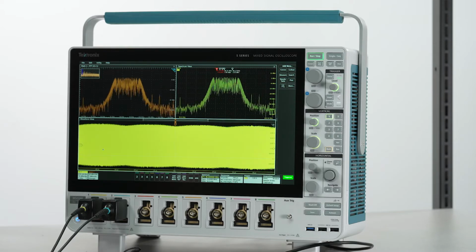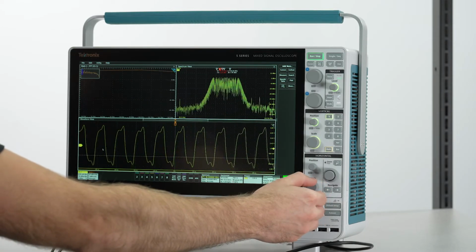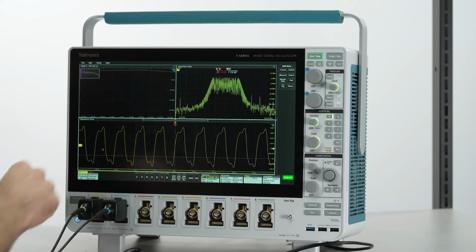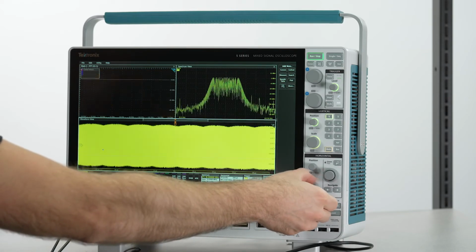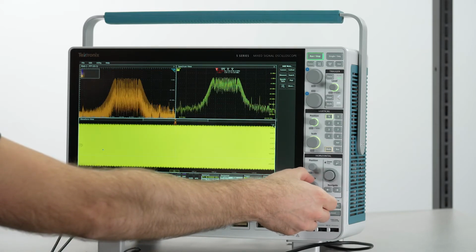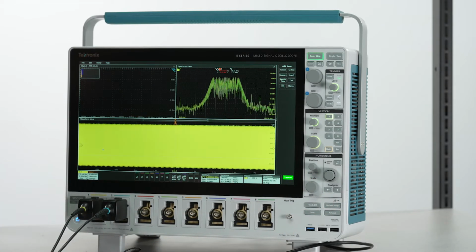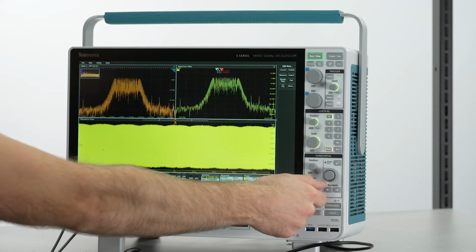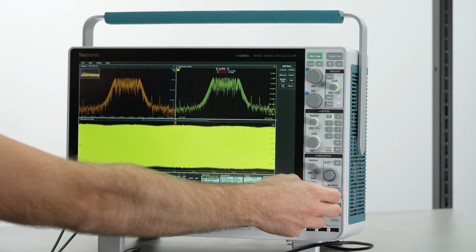And when we only want to acquire a few cycles of this clock, the traditional FFT in our top left corner doesn't have enough samples to provide meaningful data. And when we need to acquire a longer record, the FFT doesn't have enough sample rate to resolve these frequencies. Notice that throughout all setting changes, the Spectrum View display in the top right remains unchanged. It was not affected by our changes in the time domain settings.